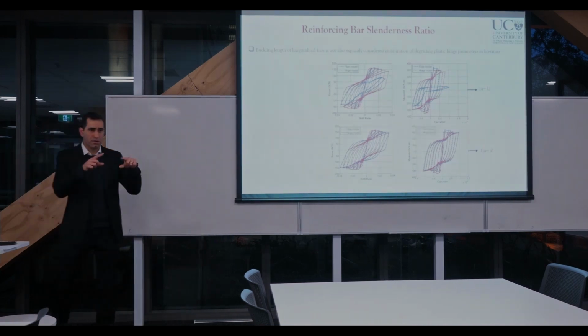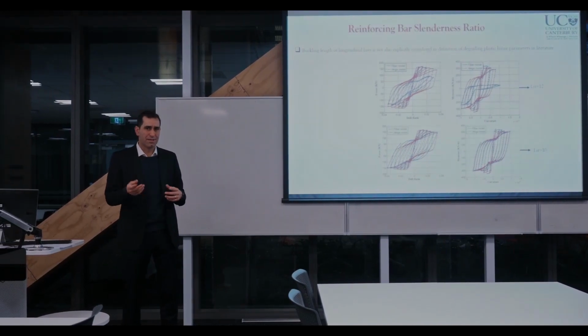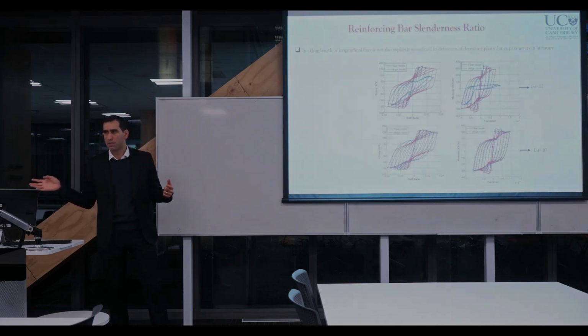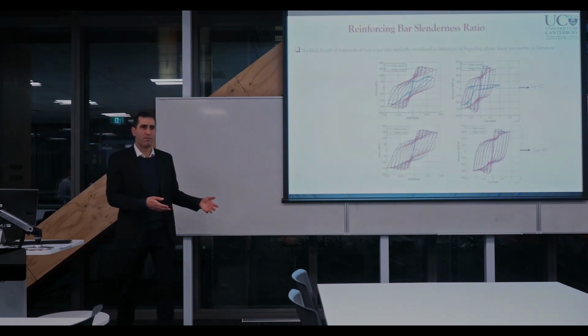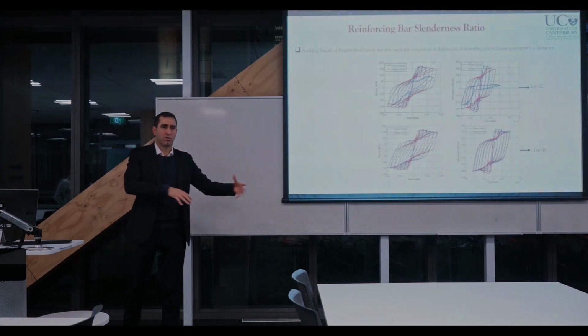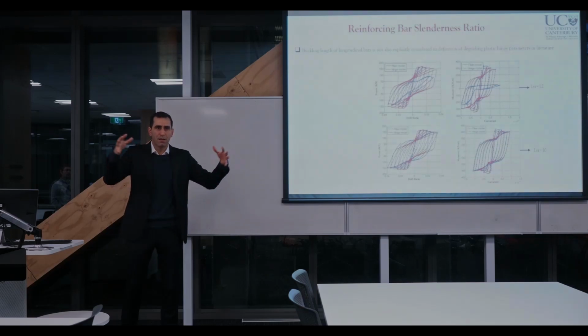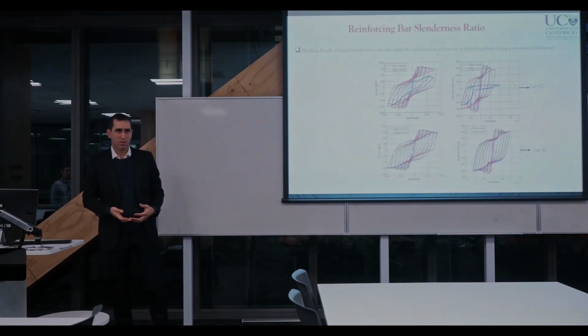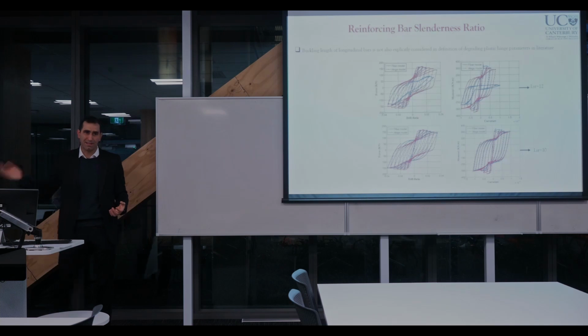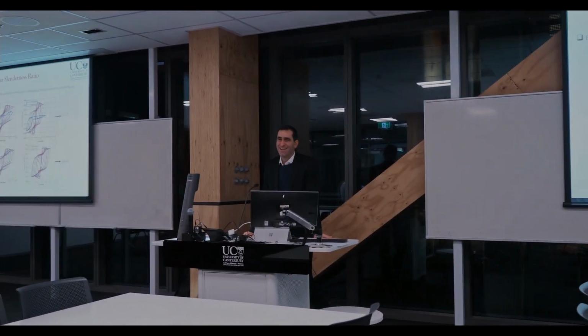If we go to those lumped plasticity models' experimental tests, you can see there is a standard deviation as high as 70%. I would imagine part of that 70%, and you can see in literature that most researchers suggest 50% uncertainties in structural modeling, could actually come from the fact that they are ignoring LSR. So in the tests, one section shows good results, and the next section, which is still conforming, is not showing very good results. So something's missing here. That could be the point. Rajesh has shown that that is the point.